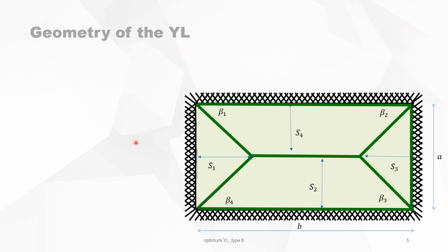Now let's look at it a little bit closer. This yield line pattern must be realistic. So that means that this point and this point must be on the same horizontal line. If not, you do not have a realistic mechanism of slab parts rotating around each other. So this means that for all the variables, the four variables that we have from the angles of the yield line pattern, we can make the following expression.